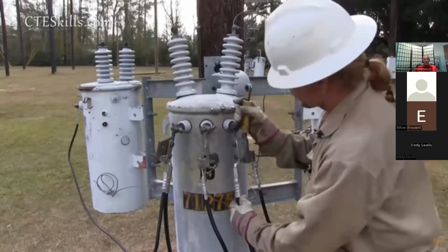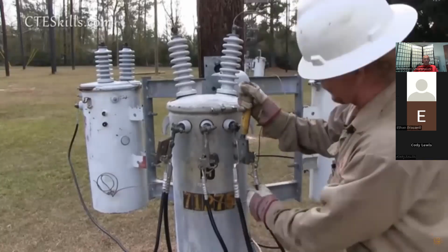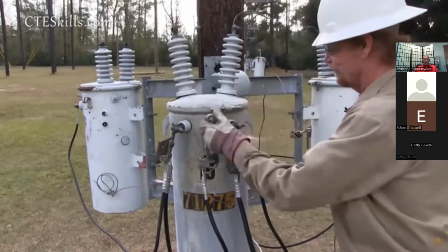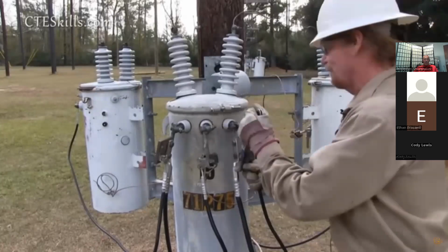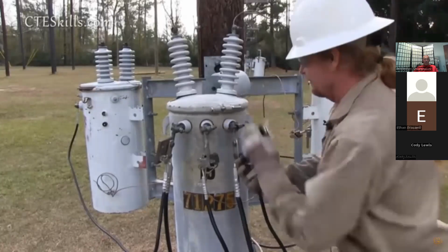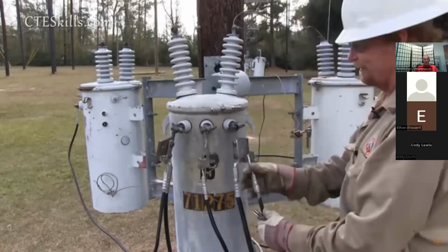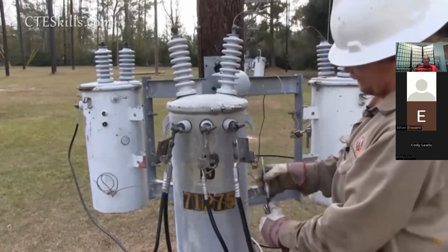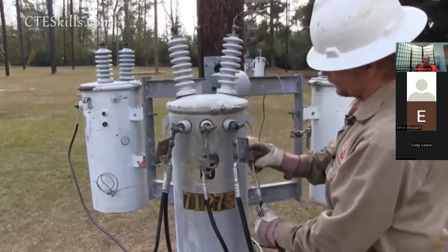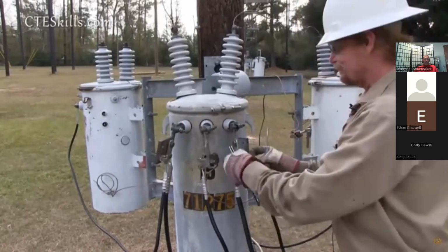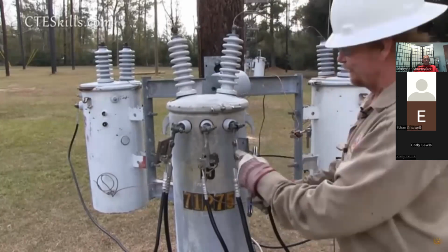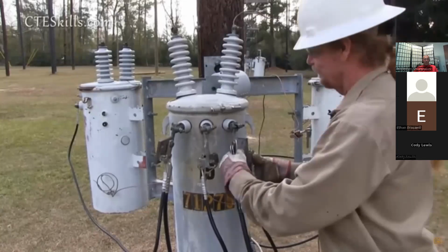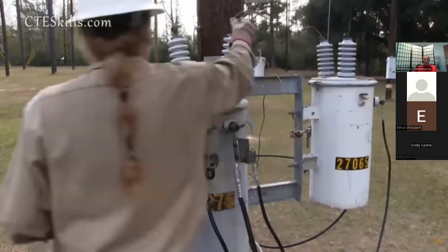We use special connectors. We have aluminum wire. These are called our pin terminals. There's a special connector used for aluminum, so aluminum will hold up, doesn't fall apart. And in this end of this pin terminal, this is called a flag. These are CT lugs. These are compression connectors. We use a special tool to press that connector on, and so it'll hold a good electrical connection, bond. Okay. And in this end is a tin copper, and then goes into brass. Brass and copper will work well together. They don't corrode.